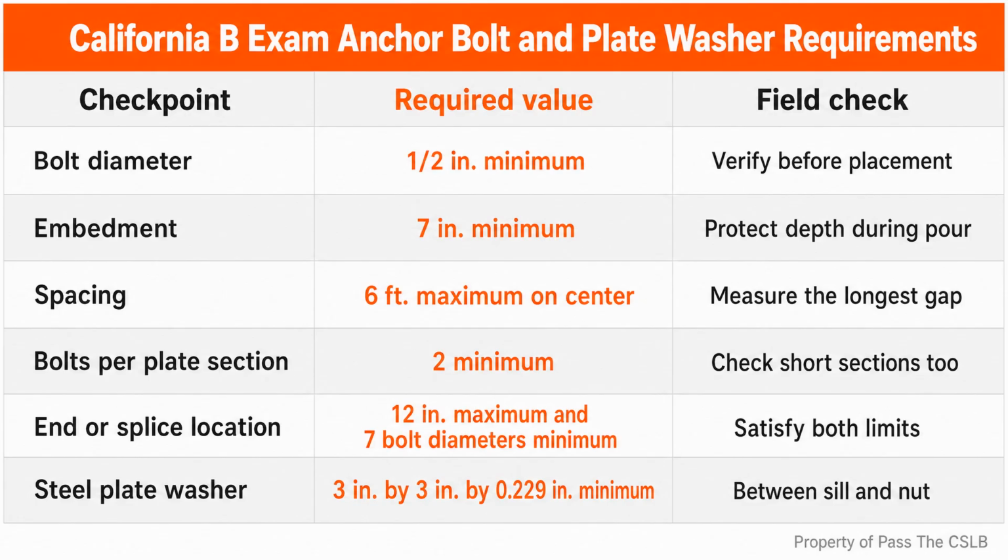A thin plastic mushroom cap may protect a hand from a scratch, but the source report does not treat that as impalement protection. Manufactured impalement covers must be approved and capable of passing a test using a 250-pound sandbag, dropped from 10 feet. The point is that the cover needs a load-spreading element strong enough to resist penetration.